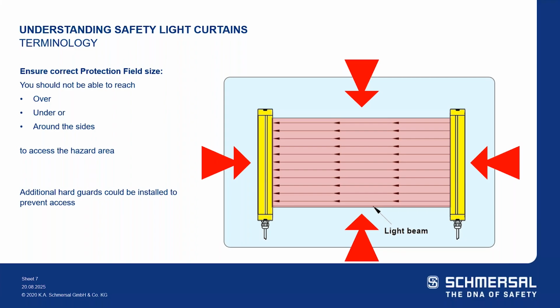You want to ensure that the protected field is of sufficient height and width, so that range, the protected height and the range, so that operators cannot reach over, reach under, or go around to reach the hazard. If so, additional hard guarding should be installed to prevent access.